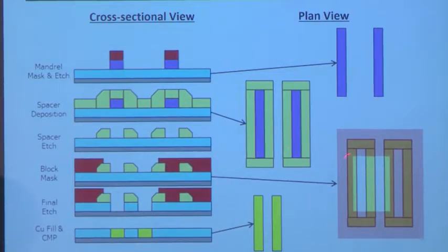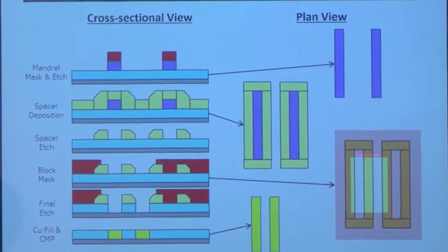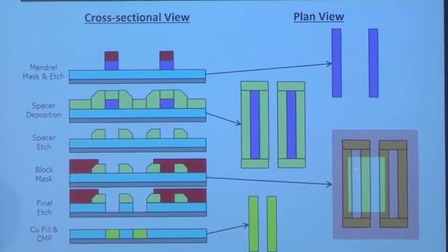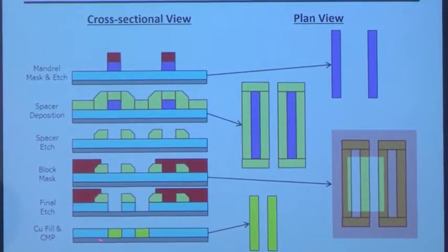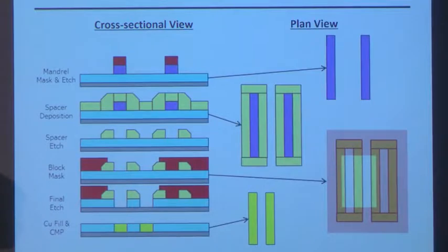This is shown in plan view here. So this is a second mask. The first mask was used to pattern these mandrels. The second mask is used to pattern the regions where you want trenches. And then you can actually end up with trenches, and then with the metal layers you can deposit copper and polish it back to form two copper lines, for example, if you want,